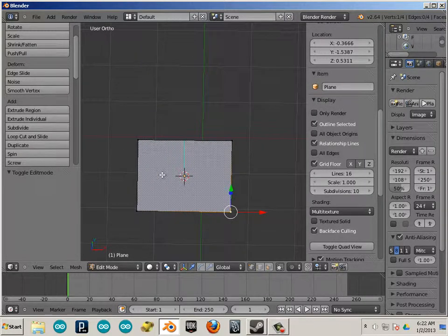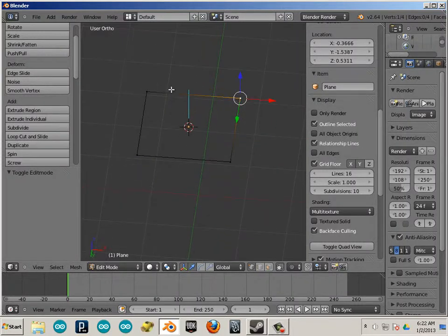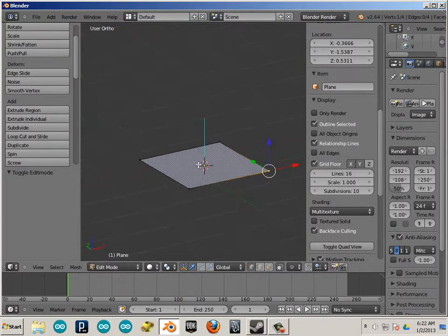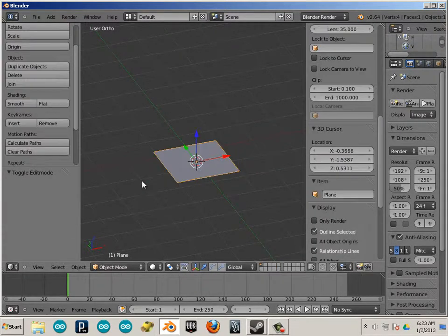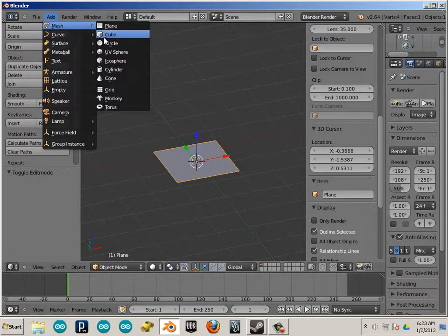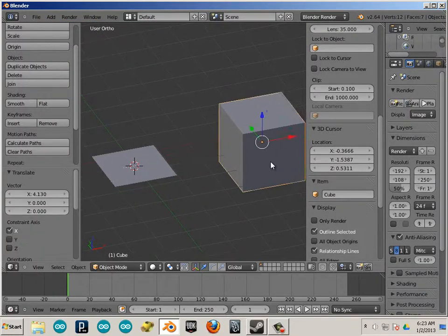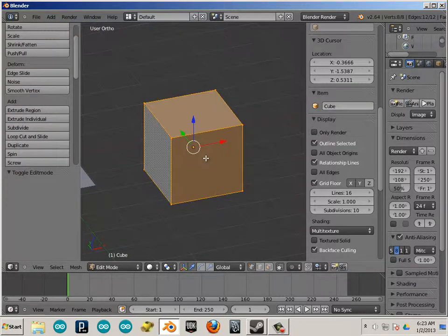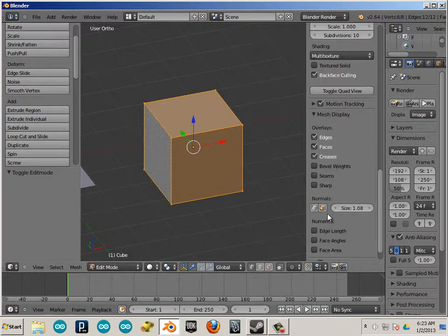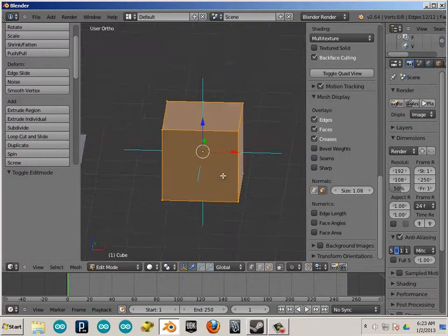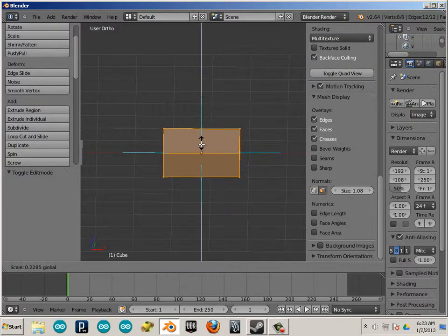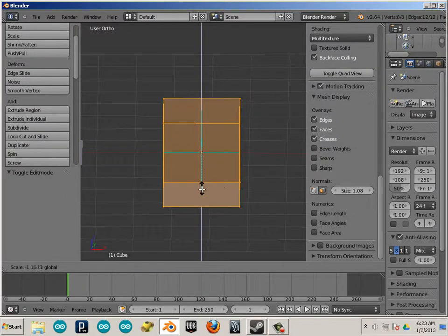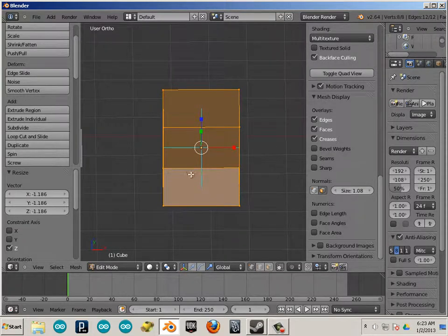Now, important, this will never show up in a 3D print because it is a single surface, not a volume. Okay, so a volume is this. This cube is a volume. And if I went to components, I could see that the face normals are all facing out. So this would show up. Now if I hit R on the keyboard and then scaled this past a certain point, the face normals will face in, and this will not print.